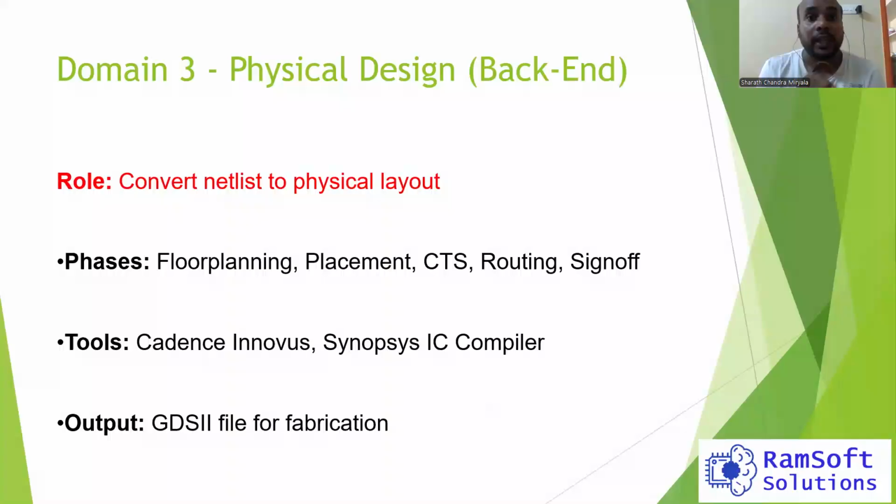In PD, literally floor planning, and then we call it PNR, placement and routing, then CTS, clock tree synthesis, and then routing. Once you are done, you need to do the sign off, which is timing closure. If it is Cadence, you use Innovus for physical design.